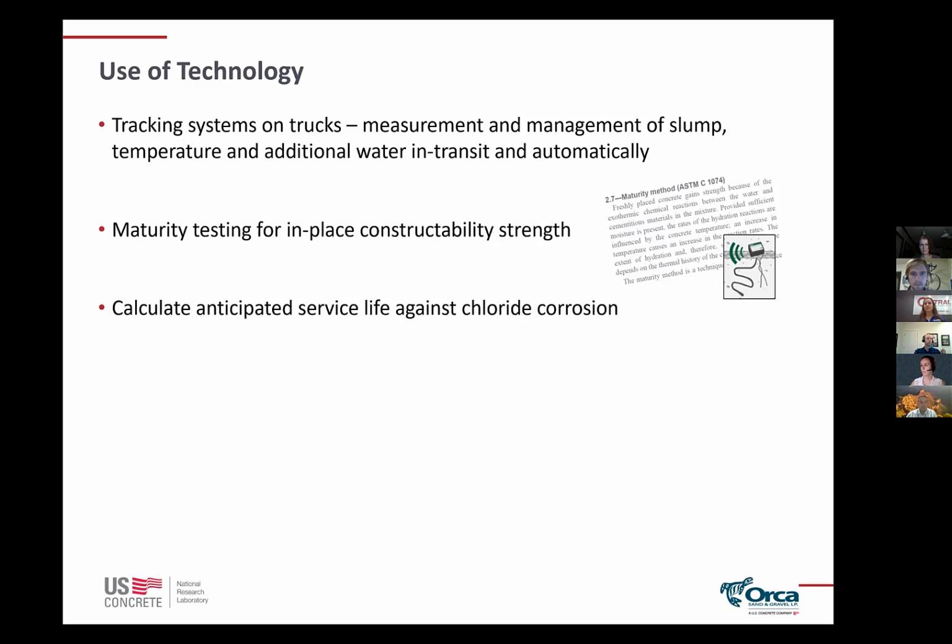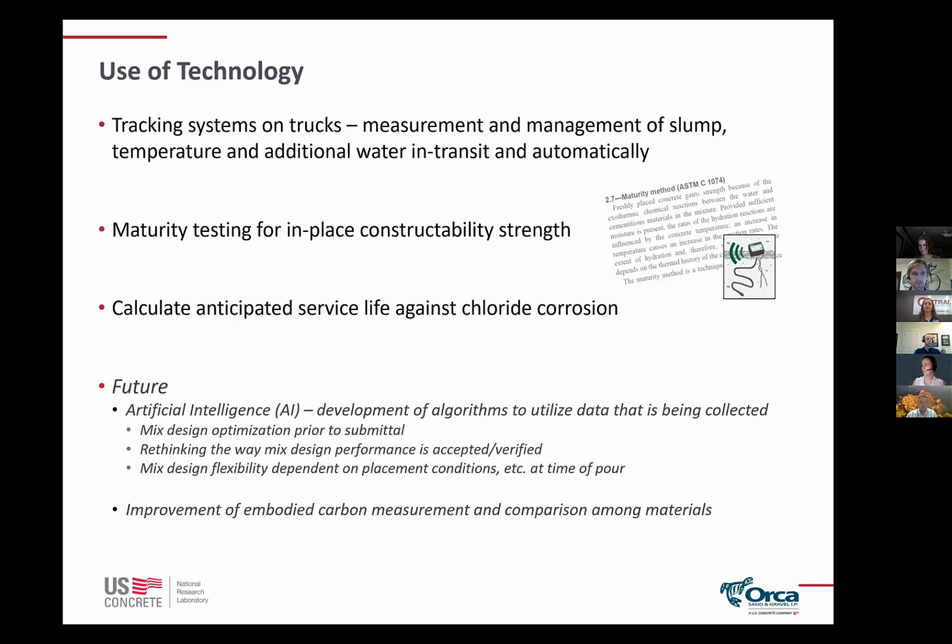Maturity testing is also a great solution for doing in-place constructability strength, and particularly when you're doing high cement replacements, this can be helpful in those applications. And then we also have programs to calculate things like the anticipated service life against chloride corrosion, and that allows us to refine mix designs.